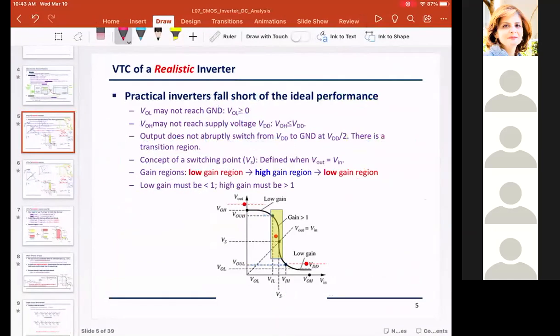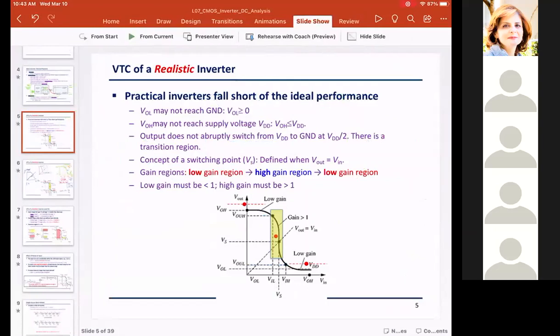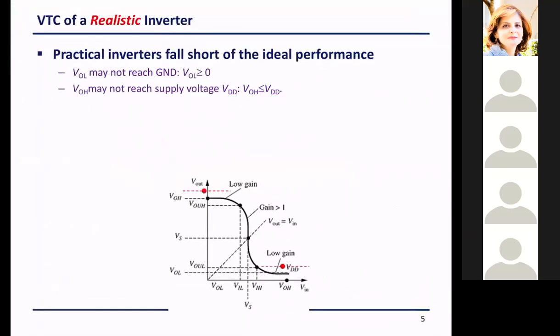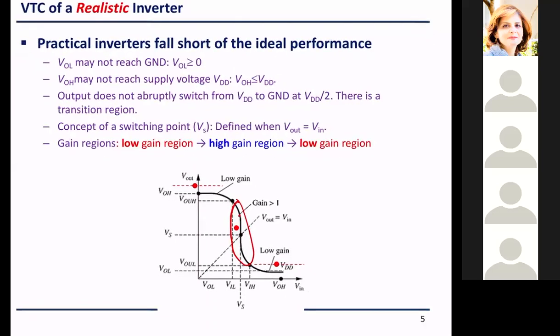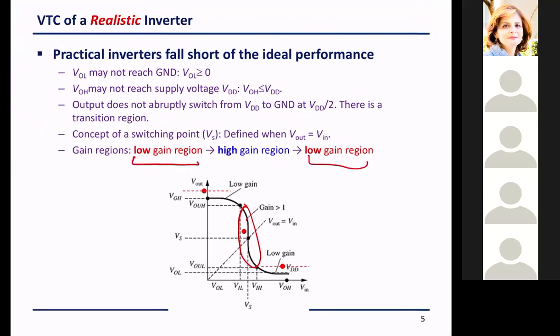So in between all of this, the region is really forbidden. Here I have this graphic that I prepared for you. In between these I have a forbidden region that I should not operate in, meaning my signal should not go there, and the output will not be defined: neither logic high nor logic low. The problem is that the noise here will have high gain, so it is going to accumulate and build up. But I cannot suppress the noise anymore. So I want to operate only in the low gain regions. That's why we restrict ourselves to this signal having only this much noise margin.